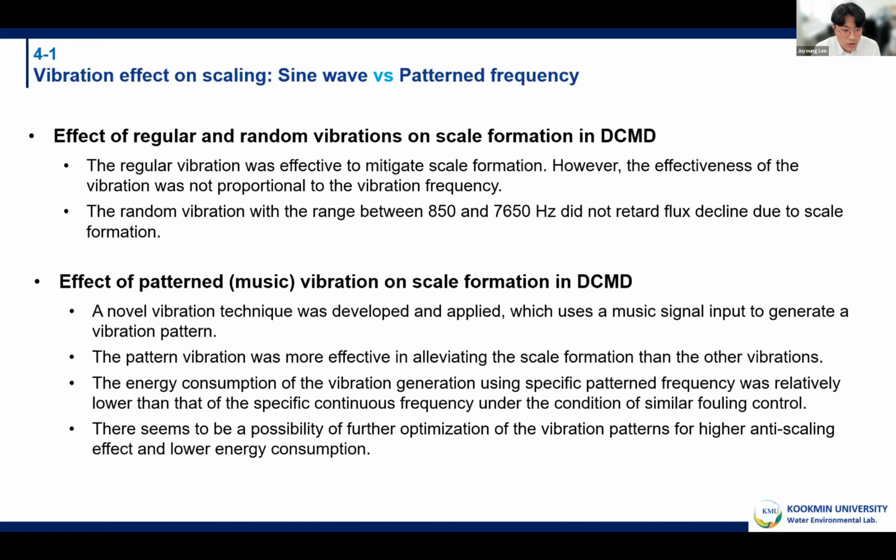The random vibration with the range between 850 and 7,650 Hz did not retard flux decline due to scale formation. We also investigated the effect of patterned vibration. The patterned vibration was more effective in alleviating the scale formation than the other vibrations.